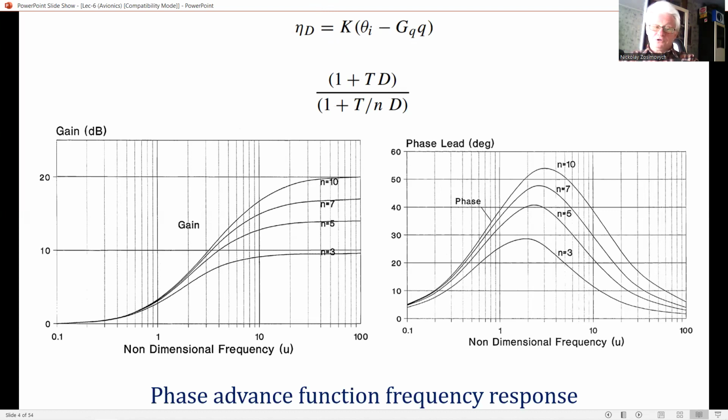Control terms proportional to the derivative or rate of change of error and integral of error are also used to shape and improve the closed loop response. A brief explanation of the action of these control terms is given below and will be used later in view of their importance in closed loop flight control systems.